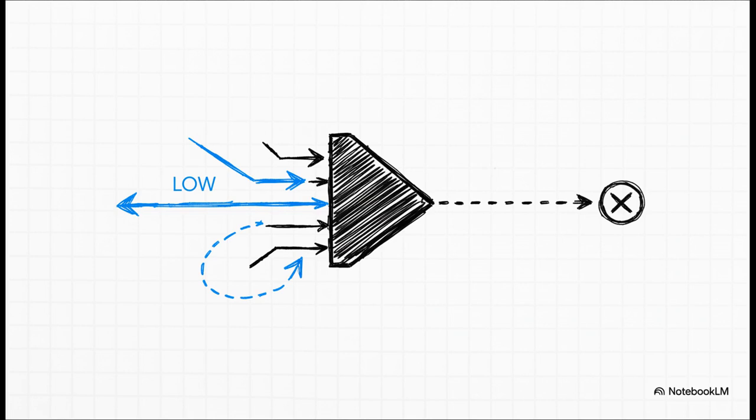Okay, the real secret weapon of TTL is this thing right here, a multi-emitter transistor. It's kind of like having multiple input diodes all mashed into one super efficient component. And here's the clever part. If any one of those inputs goes low, this transistor immediately yanks the current away, basically starving the next transistor Q2 and forcing it to shut down. It's an incredibly smart design, like a bouncer at a club.